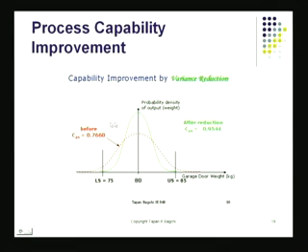This process is clearly not capable, and the CPK measure here turns out to be 0.766, which is less than 1. I can improve this process, and here I can do that because centrality is not an issue. The old process also is really right on target. The average x double bar is standing right at the target, no issue there.